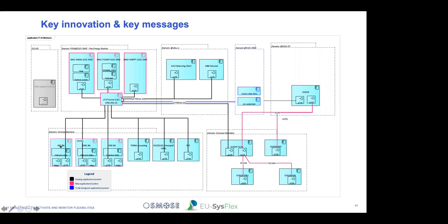So all this data is then, of course, gathered and calculated, and the output of this flex energy management platform is the so-called flex energy bid, which then goes into the SFTP ELES output server, which you can see here with my cursor. And then this activation signal goes via SFTP protocol into the ELES TSO SCADA production environment, where it is transformed into the ICCP signal, the activation signal, which goes then from the ELES ICCP channel